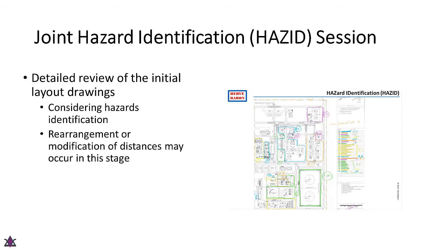This involves the different engineering units, where they look at it critically based on the different codes of practice. Areas of the layout which pass the different recommendations are given a go ahead, and the ones which need to be reviewed or repositioned are marked out, as you can see there on the screen. So the different units, the ones that pass, the ones that don't pass, and the ones that need to be additionally scrutinized or analyzed are all indicated during this HAZID process.